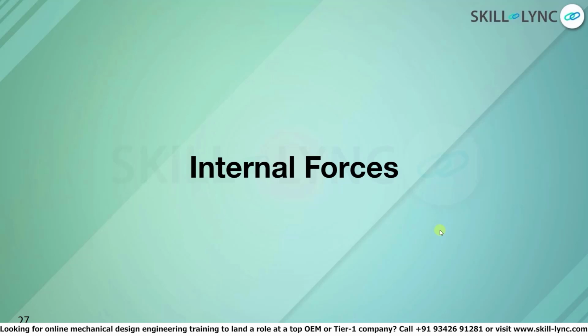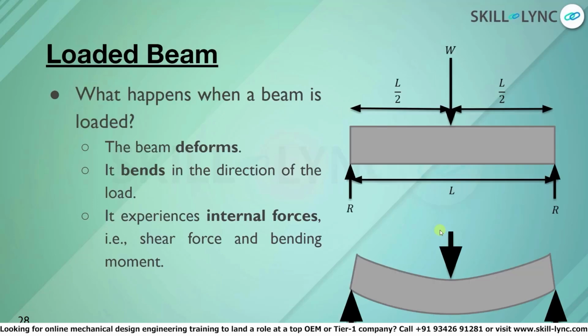So for this topic, we will be looking at how to calculate internal forces that are generated because of loading. The internal forces that exist in beams are shear force and bending moment. We will learn how to calculate them and plot them graphically. These graphs are called shear force diagrams and bending moment diagrams. They can also be shortened as SFD and BMD, wherein SFD is shear force diagram and BMD is bending moment diagram.